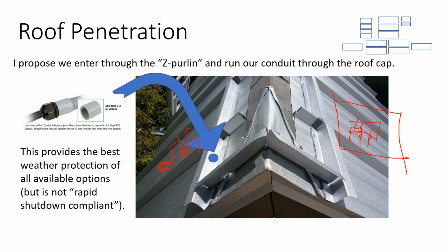We did have one leak because the installation crew failed to seal the inside of the block. And what happens when water runs down this, it didn't get into the pipe boot, but the water actually climbed up the pipe boot and started getting into where the conduit and the box intercepted. So we had to take the module off, open the box back, and apply some sealant around that penetration of where the conduit and the box hit. So I didn't really like that solution. Could we improve it?